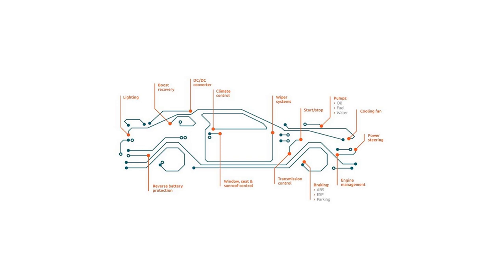They play an important role in the control of this application area: mirror folding control, for example, window lifter, drill machine, seat control, sunroof control, because the DC motor is very cheap. However, brushless DC motors and permanent magnet motors are very expensive compared to the DC motor.